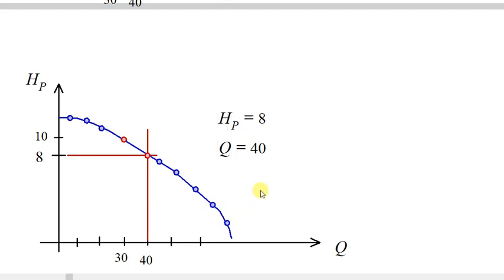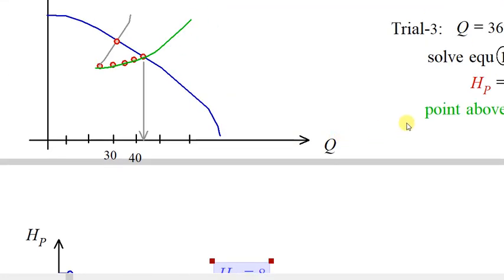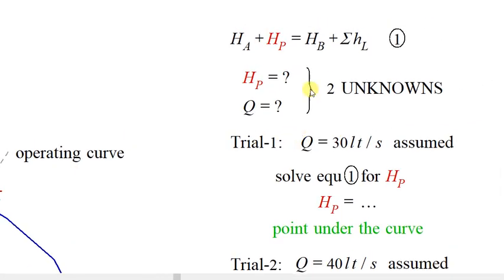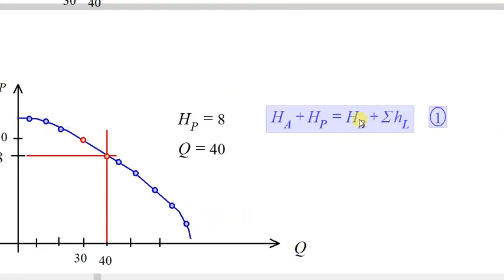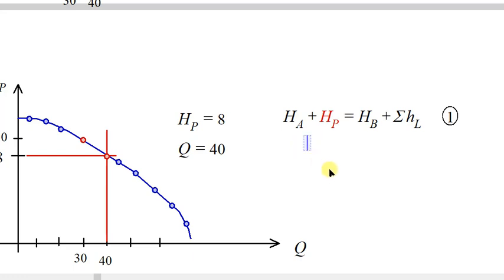The only case this works is that after you choose HP and Q, you bring the Bernoulli equation and make sure whatever answer you get on the left is equal to the one on the right. For example, if it was 20 equals 20, okay, then you can approve this. You can say, okay, the solution is correct.